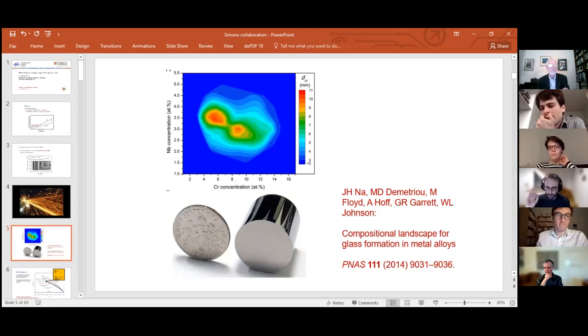Just a quick other one. It seems that the elastic properties are not really affected by this extreme rejuvenation. Is that true, or is it just a feeling from the curve? I suspect that this dramatically depends on the treatment. So if we do our thermal cycling treatment, we know that there's a quite measurable change in some type of mechanical property. And as I mentioned, maybe something like the toughness could even be doubled as a result of that treatment. In contrast, the elastic moduli are hardly touched at all.